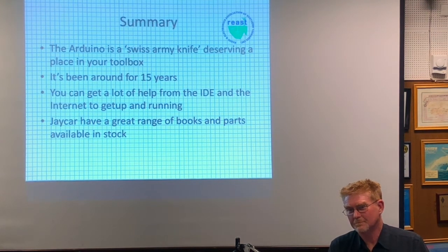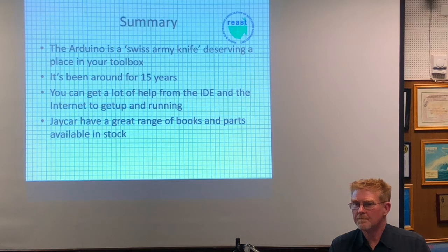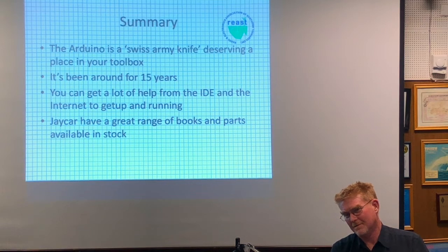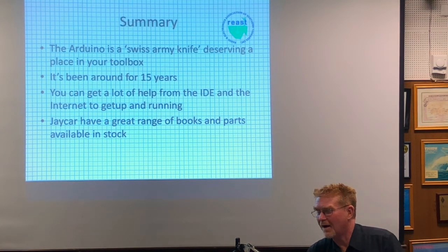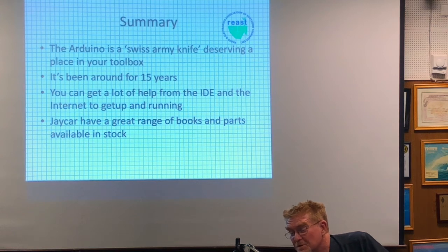And my intention is, if my skill set ever gets good enough and I take enough Valium to not jiggle around, I should be able to put a 10 megahertz reference into the XA, which will overdrive it, and you'll have 10 meg GPSDO locked with pretty much any frequency you want up to 200 megs with GPS locked. It's doable, by the way. I fully believe it's doable.